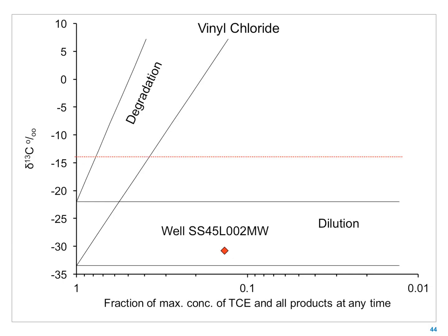And you'll see that the vinyl chloride falls way down in that dilution and dispersion part of the graph, so there is no evidence in this data that there's biodegradation of vinyl chloride occurring in the groundwater as sampled. Notice I didn't say that it's not degrading. The CSIA cannot prove a negative.